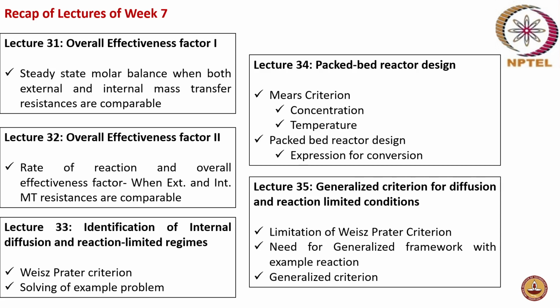So in this lecture, the limitation of the Weiss-Prater criterion was discussed, and a need for a generalized framework was explained based on the example of conversion of CO2 to carbon monoxide reaction, where the Weiss-Prater criterion failed to indicate that the reaction is actually limited by the internal diffusion.